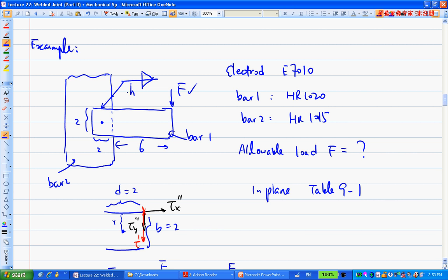So, basically the same calculation, right? Now the only unknown is H. So in the end, you calculate the H value, right? The only catch at the end is, when you calculate H, you probably will get a decimal number, who knows, maybe 0.22, for example, right? So when you choose the H, it's like a design question. Then you choose the next legitimate fraction size, the nominal size in fraction. So I would choose a quarter, right?